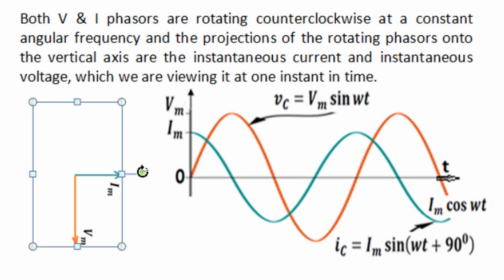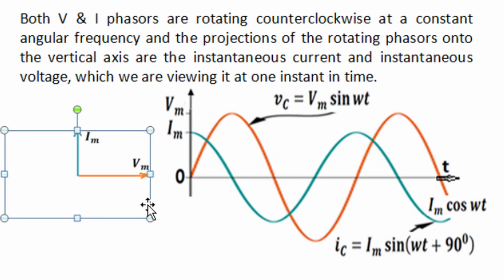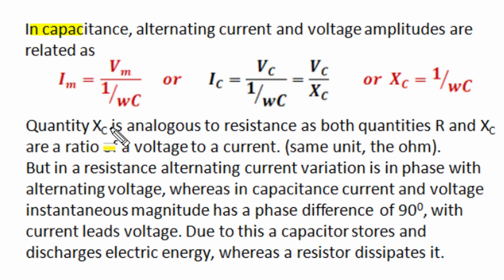As time progresses and the phasor rotates, the current becomes charging current and negative charge and potential of the capacitor reduce and become 0 when charging current becomes peak. So we got that voltage and charge alteration is sinusoidal alteration and charging current is co-sinusoidal alteration, and in sine and cos, when one gets peak magnitude, whether it is positive or negative, the other gets 0 instantaneous magnitude and vice versa.